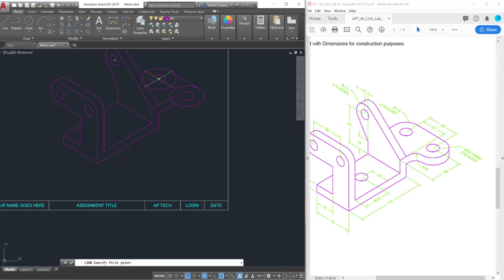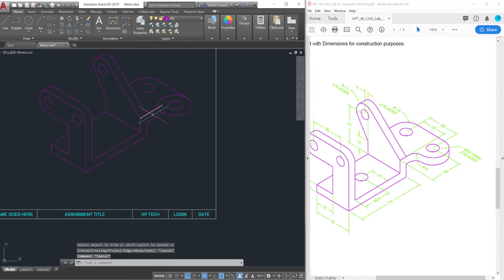I'm going to do the same thing here. Move the last object a distance of 15 that way. So you may notice I invoked the last option to select that last line I drew. I'm going to trim out this ellipse that I don't need, and I'm going to trim out this line here with that. And I'm almost done with this.